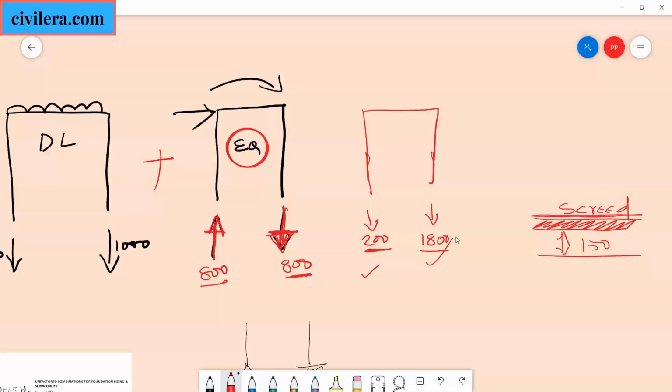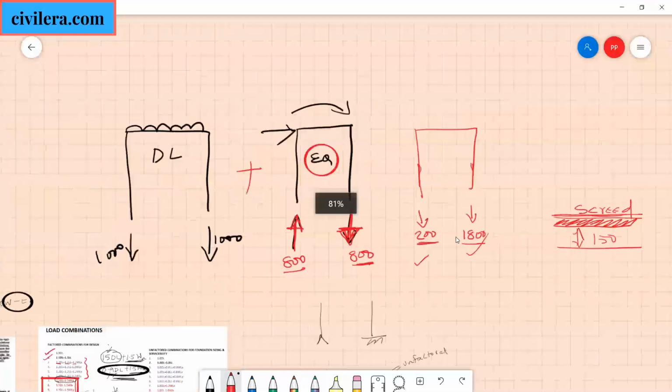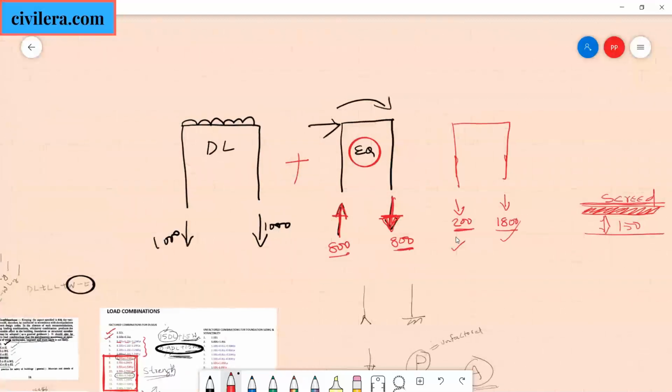Now he will think that, okay, load is reducing, so why should I inform the structural engineer? And in many cases he will not. And many times a reduction in load is always considered to be really good for a layman. So what really happens there is you don't have 1000 there, because the client, without telling you, has reduced the load.